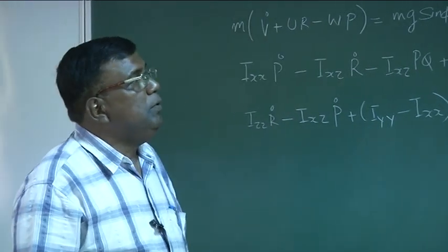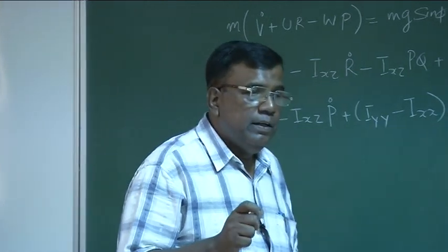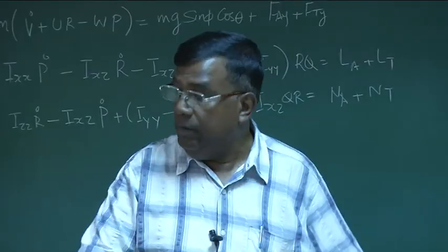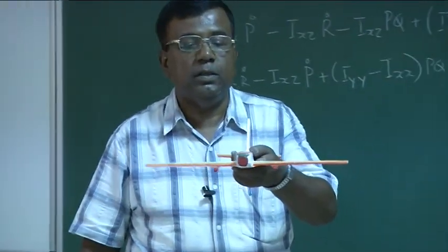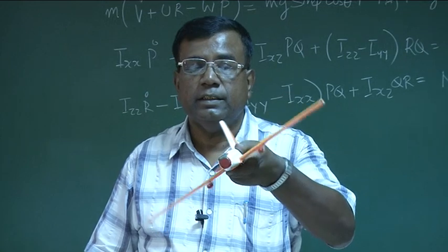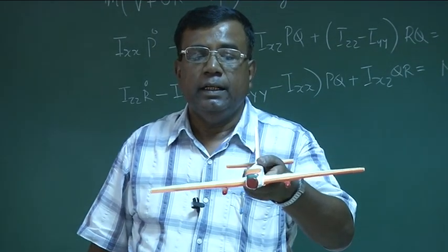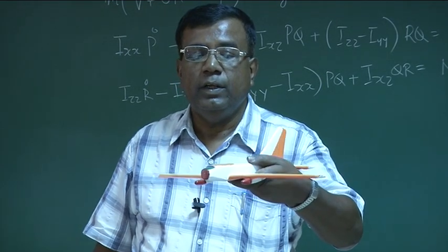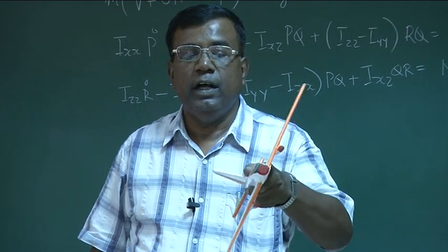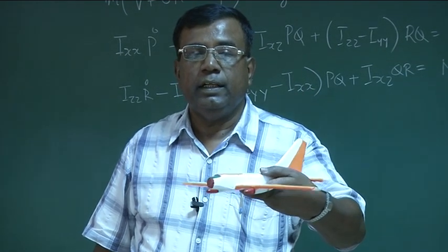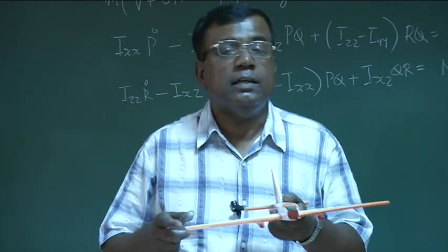Okay? We will be doing a similar thing for the lateral directional case, but with a difference. First of all, let us understand that when I say lateral motion, it means motion about the x-axis, and right wing going down is the positive bank. And directional is the right wing going back this way. So lateral is right wing going down, and this is the right wing going like this when I'm flying in this direction. These two modes are generally coupled.